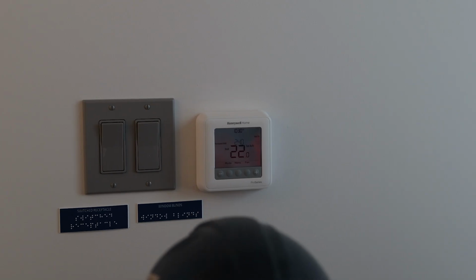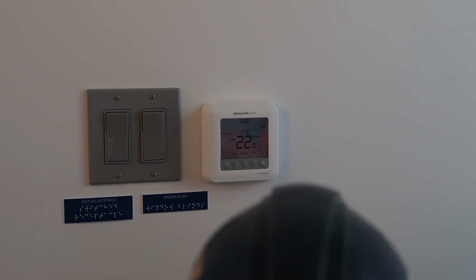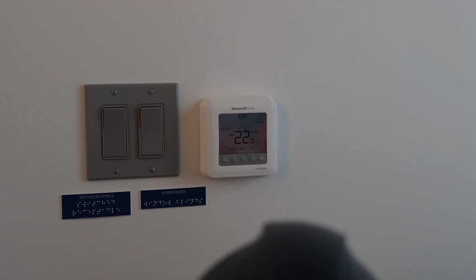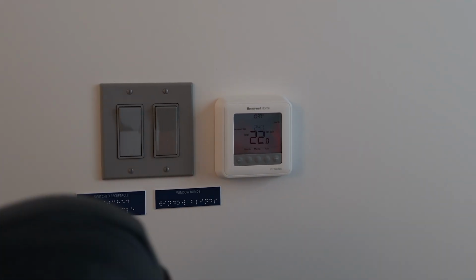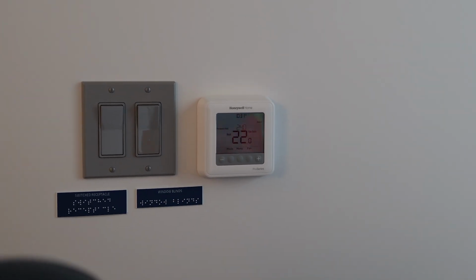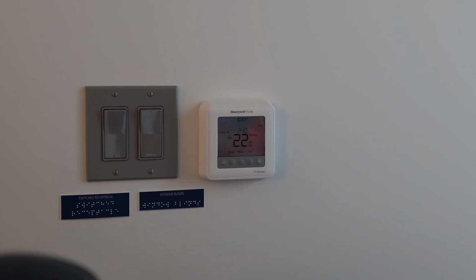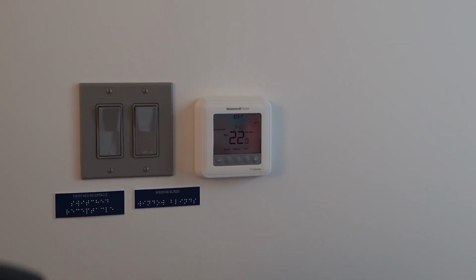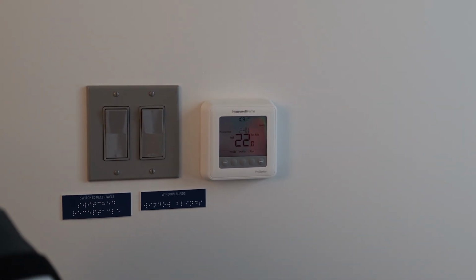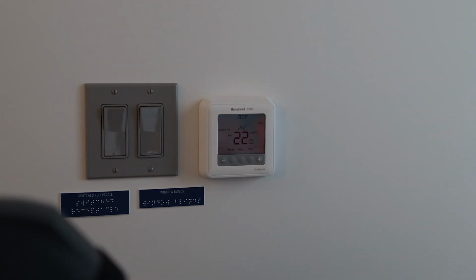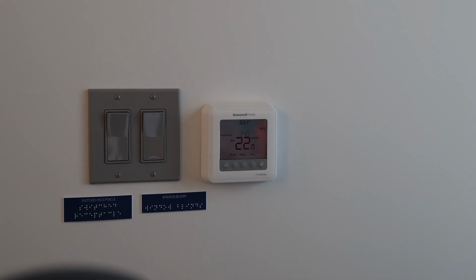And I believe there is another, the installation guide, which will allow us to access the higher level of changing the set point. For example, what's the minimum set point? What's the maximum set point? Right now it's 25 and 18. If you want to increase that to 28, I will have to send you the menu. You can go over the menu. It tells you which parameter, what it means, what the range is, and what settings you will be doing.